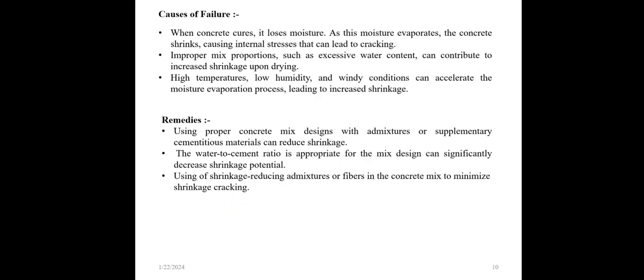Causes of failure. When concrete cures, it loses moisture. As the moisture evaporates, the concrete shrinks, causing internal stress that can lead to cracking. Improper mix proportion, such as excessive water content, can contribute to increased shrinkage upon drying. High temperature, low humidity, and windy conditions can accelerate the moisture evaporation process, leading to increased shrinkage.